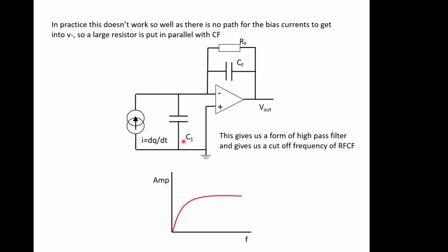Right, so we've talked about bias currents. We need to introduce a resistor to allow bias currents, because otherwise there's no mechanism really for getting a direct current in, because remember, this is a differential. This current is related to the rate of change of charge, so we can't assume that there's the availability of a constant current in here, because this is just a model of our system.